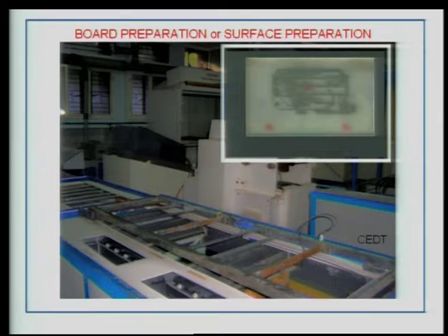The green color that we are normally used to seeing in a finished PCB is basically the color of the solder mask material. So, we will now see how a copper clad laminate, which is the starting material, needs to be readied for transfer of image from the mask that you have manufactured pertaining to your design onto the surface of copper.